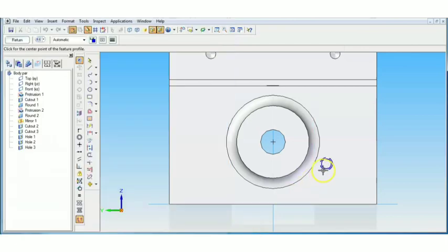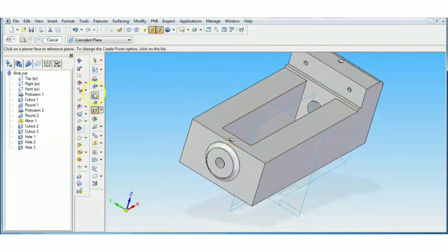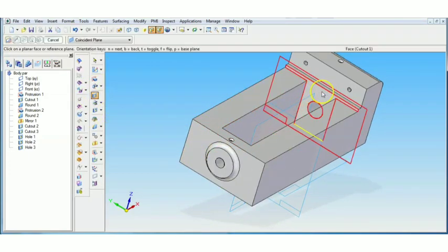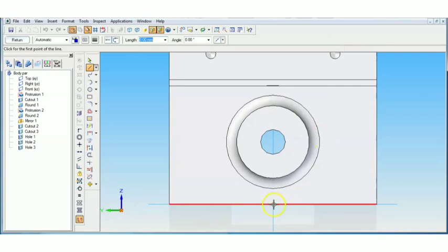So go to Solid Edge, take a line. We have to select the cutout command, we did not select it, so I'll go return. Start with the cutout command, select this plane. From this point, it is 30, enter, and 0, enter. Sorry, the line did not start from the center.